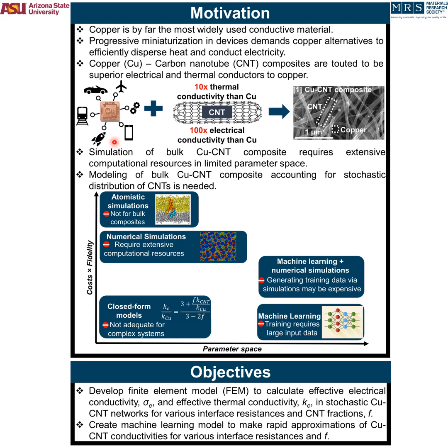As things are getting scaled down, we need better alternatives to copper to maintain device functionality at high currents and temperatures. Single-wall carbon nanotubes or CNTs are approximately 100 times more electrically conductive and 10 times more thermally conductive than copper. Therefore, researchers are very interested in fabricating copper CNT composites, which are theoretically proven to be superior electrical and thermal conductors than copper.